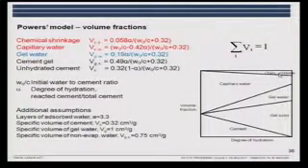And in addition, some of the capillary pores are becoming empty due to chemical shrinkage. They can be refilled if we have an open system. If we have small samples, keep them saturated, these pores can be refilled. If we have a huge sample, the water can't penetrate, or if we don't keep it saturated, we have no water.